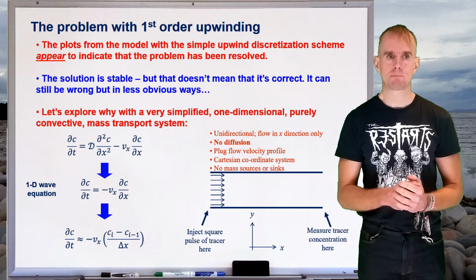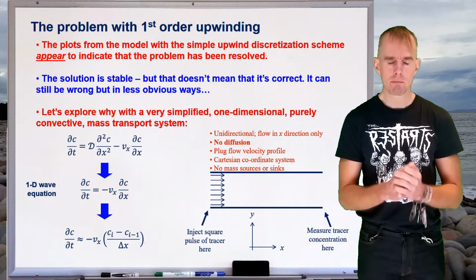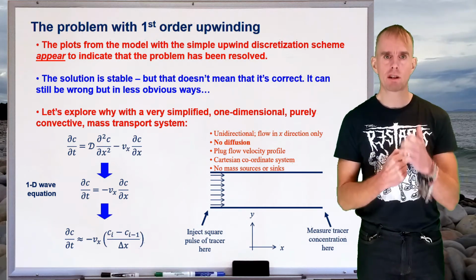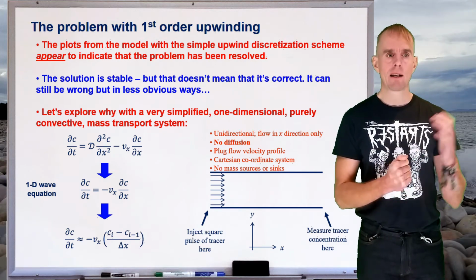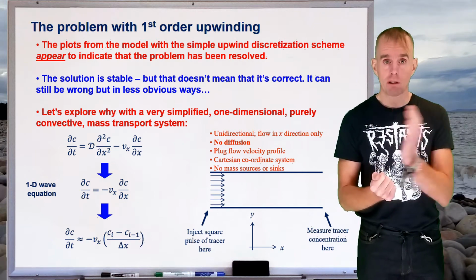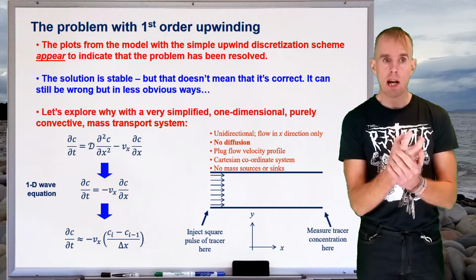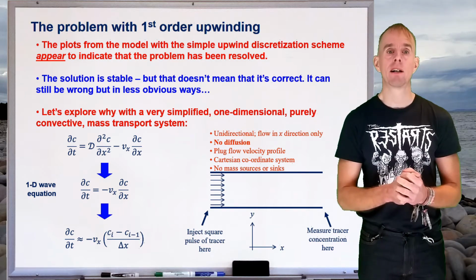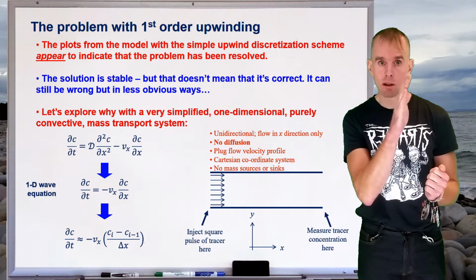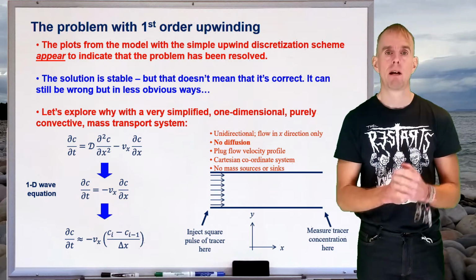The only gradients, again, in common with the thermal problem, are going to be in the x direction. What I'm going to do in my mental model is get a syringe of tracer, a nice coloured liquid, and in the colourless liquid, say water, that flows through this slot, I'm going to inject a square pulse of coloured dye at the start. And then I'm going to look at how that coloured liquid transports in the problem.